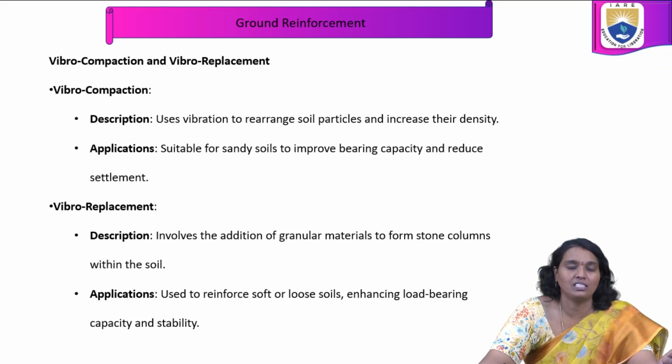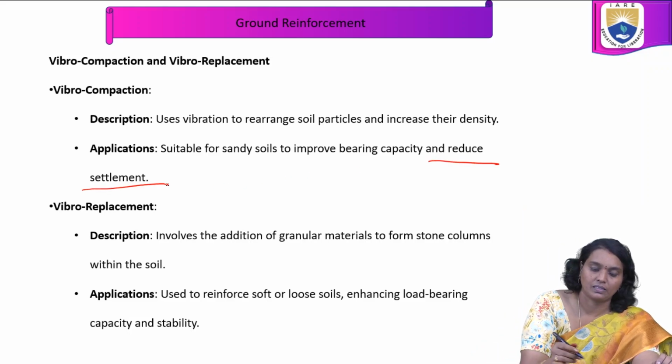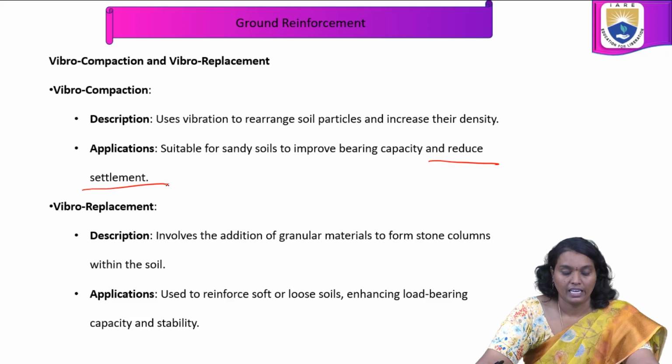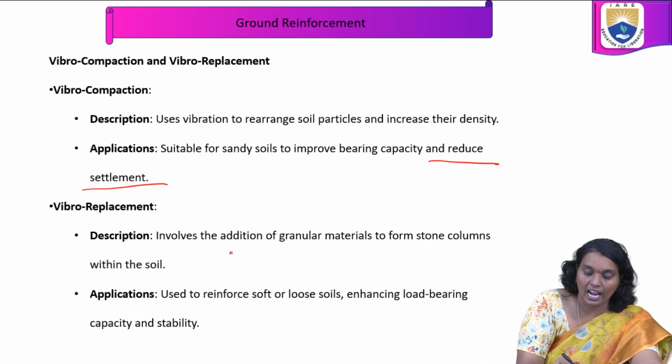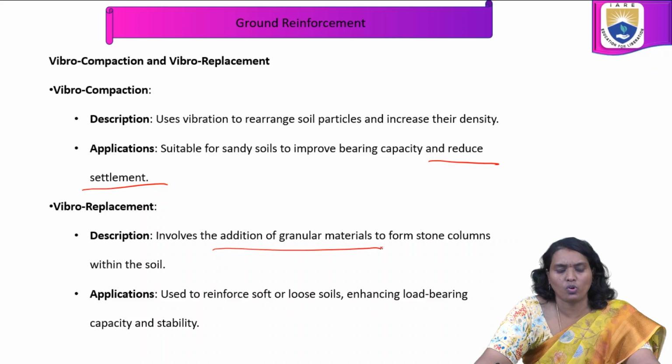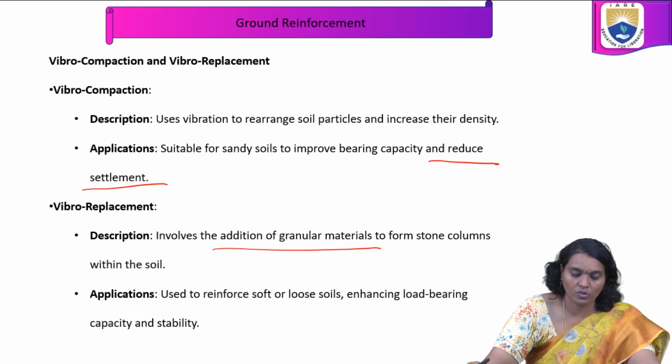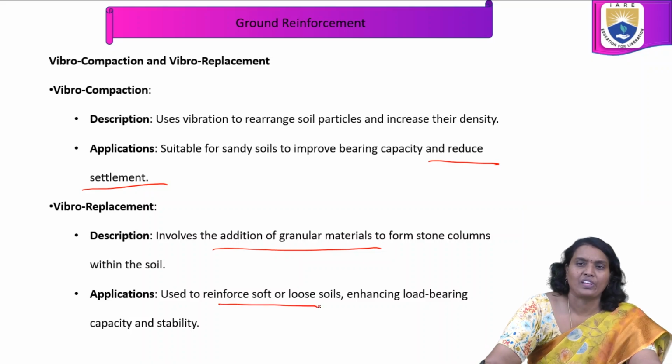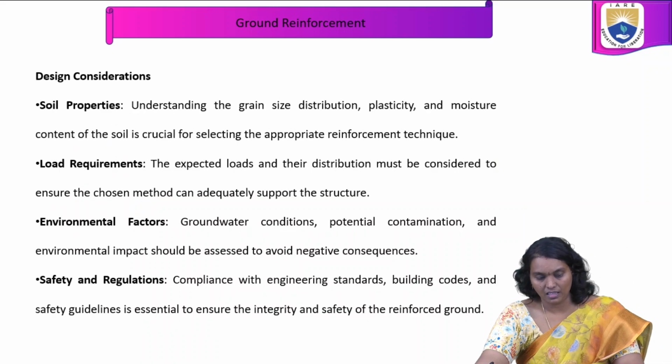In this, vibrations rearrange the soil particles and increase their density. Vibro compaction is applicable for sandy soils to improve bearing capacity and also reduce settlements. Vibro replacement involves the addition of granular materials to form stone columns within the soil. It is used to reinforce soft or loose soils, enhancing bearing capacity and stability.